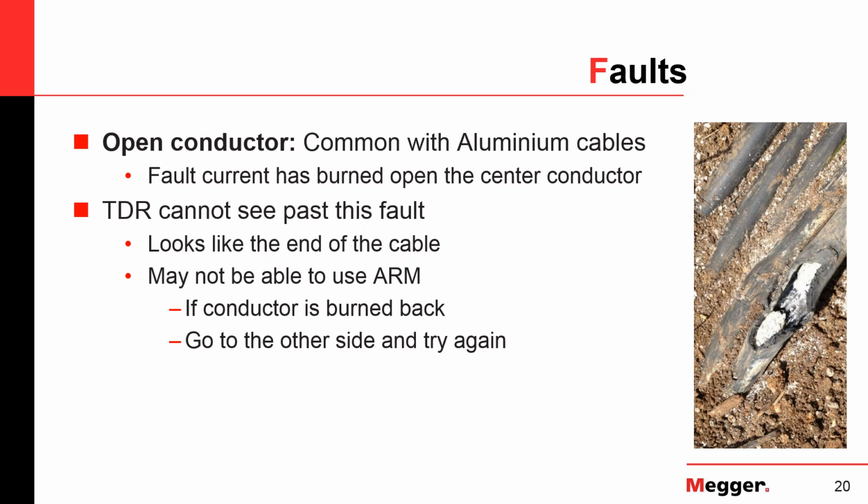The typical solution in the practical world would be, okay, if you limit it to this point, just go to the other end of the cable, because typically the cables, as we discussed, are isolated, grounded, stood off, parked. So you can go to the other side and try your fault location techniques from the other side and hope.